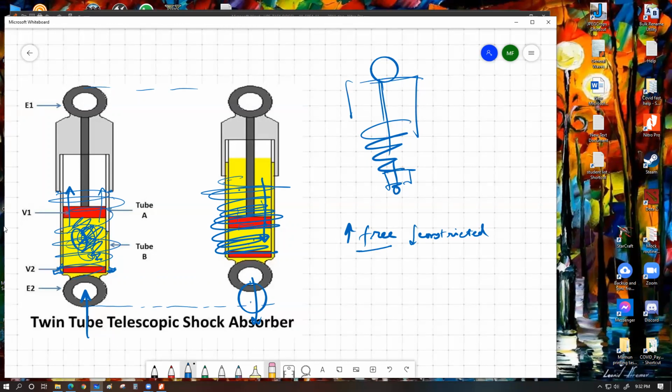Okay, what is the benefit of this? The benefit is, once the shock absorber goes to the upper position, it would somewhat apparently look like this thing is locked over here. I mean, it's going to jump from this position to this position pretty fast whenever it will experience the upward force, but it will come back from this position once again to the original position over a really long duration.